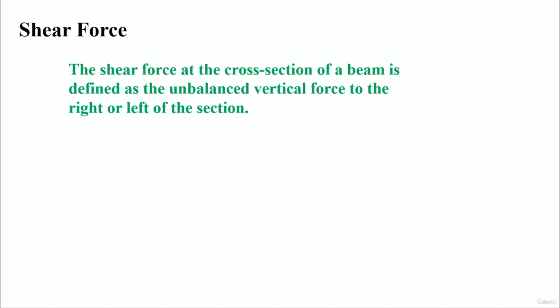Another important term is shear force. Shear force is also the internal force which is developed due to the application of external load. The definition of the shear force is the unbalanced vertical force to the right or left of the section. The shear force at any cross section of a beam is defined as the unbalanced vertical force to the right or left of the section.